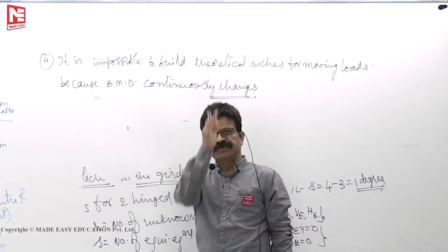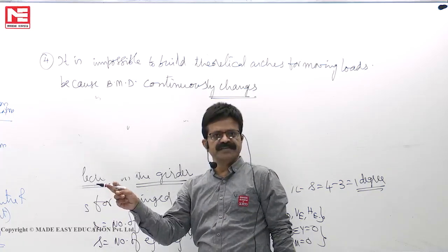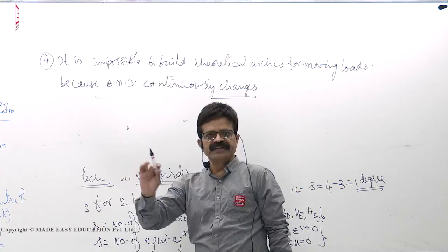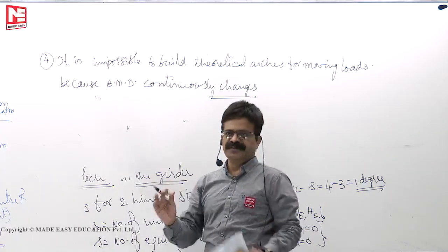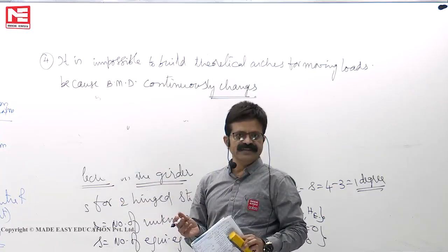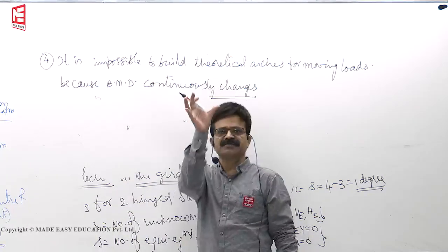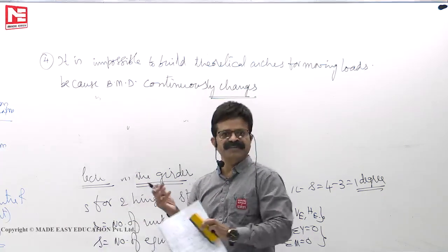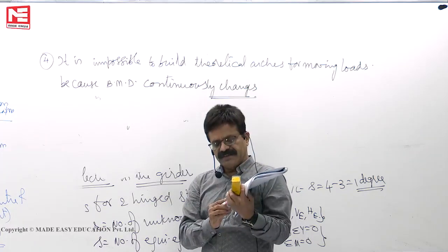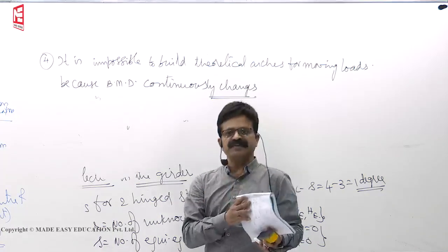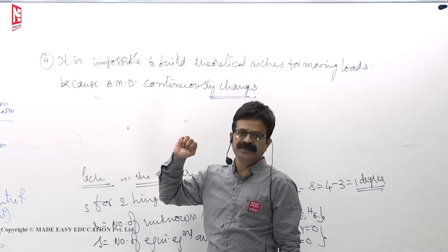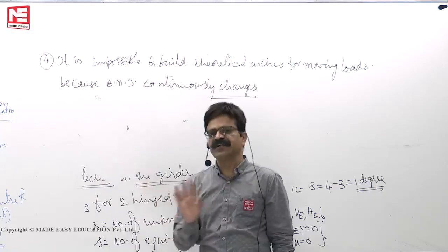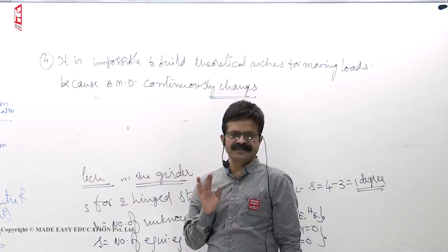For stationary loads, once the load is fixed, the bending moment is fixed, then if you build the structure in that shape, fine. But if the loads are moving, then the bending moment will also change, depending on the position of the load. You have already built one structure corresponding to one particular position of the load. If the loads move, the shape will not change, but the bending moment changes. So naturally, the theoretical arch behavior will be gone because there will be shear force and bending moment in the structure. That's why you cannot build theoretical arches for moving loads, because bending moments will change.